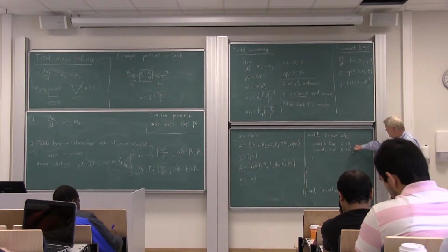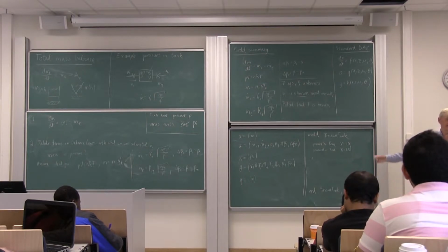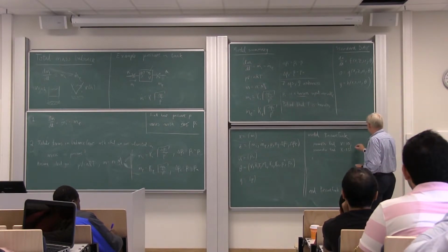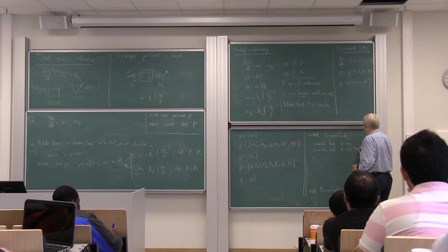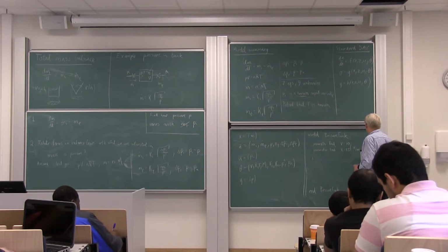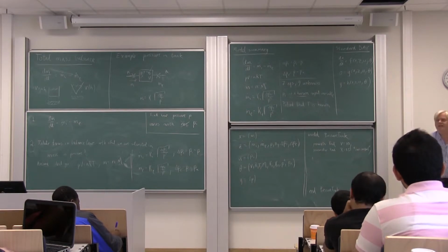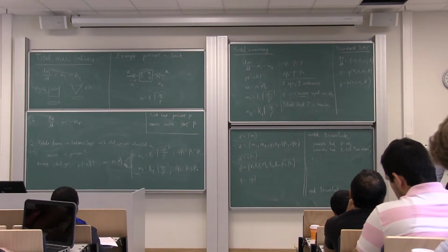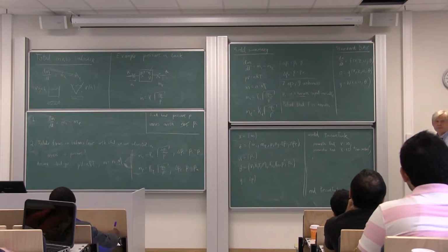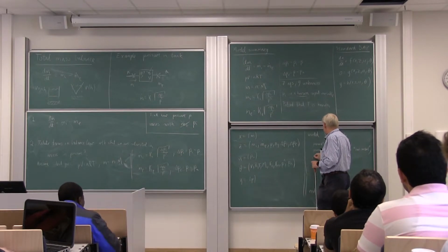If you want to, you can add a comment, but that's up to you. You don't have to, but you could, and you put that in as a string, gas constant, for example. That's voluntary. You can add a text that describes what it is, and it's recommended to do that. It's also recommended to include the unit in this string, just to make sure that you document what you're doing. And so on, all the way to